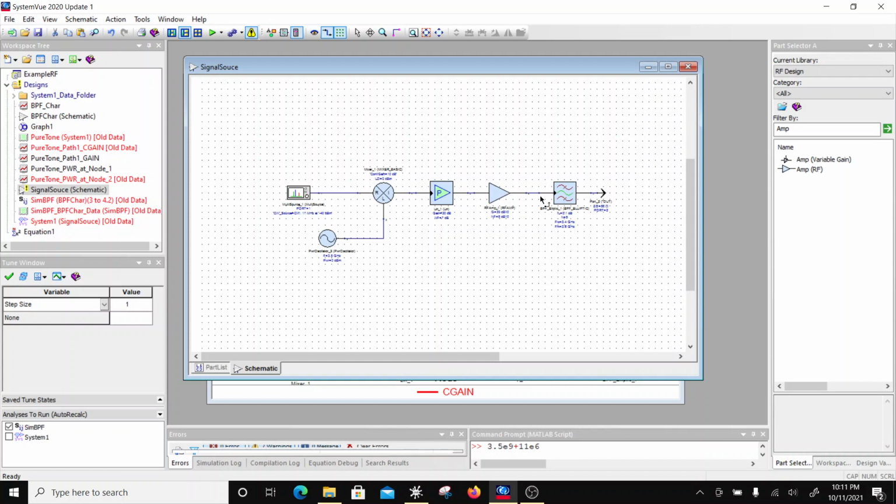That's there. Now even order mixing is more important for a receiver than the odd order mixing, and we will talk about it, and this is true in case of heterodyne receivers. Okay, in homodyne receivers you have even as well as odd order mixing important. Both are important, but in a heterodyne receiver, the even order mixing is more important than the odd order mixing.